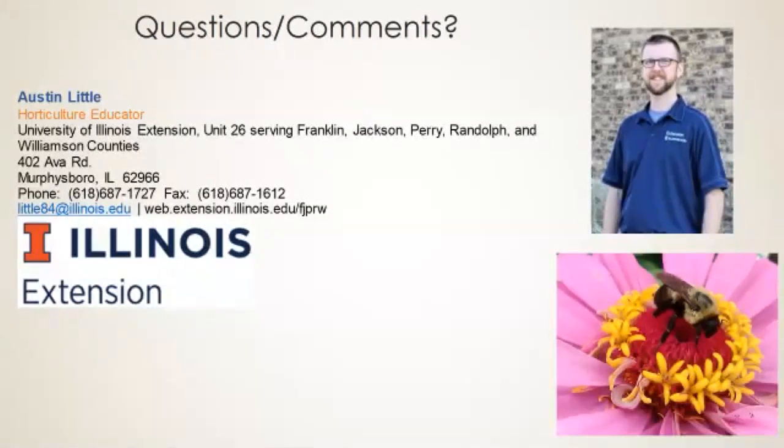One person asked, what is the maintenance for each of these systems in a northern climate with the snow and ice? Well, these permeable pavers and pervious pavement systems need less salt on them. They move snow and ice away from the pavement faster, so they don't need as much de-icer and salt, because they've got more airspace in there, so they warm up faster. But the maintenance part of it is going to be pretty much the same.